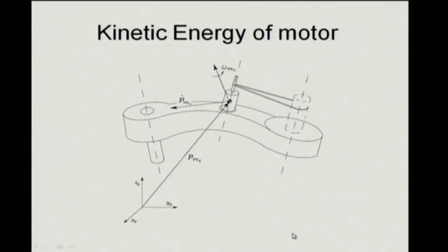Now, when we are talking about the motor, so there are two parts, right, this stator part and the rotor part. Now, this is a very schematic diagram. The rotor is not necessarily a thin spindle which is sticking out. The rotor internally, it has windings on it. Okay, so there are two kinds of motors which are there, moving magnet and moving coil. Okay. So, originally motors used to be moving coil, but now they have often become moving magnet motors, especially the high torque motors are often moving magnet.